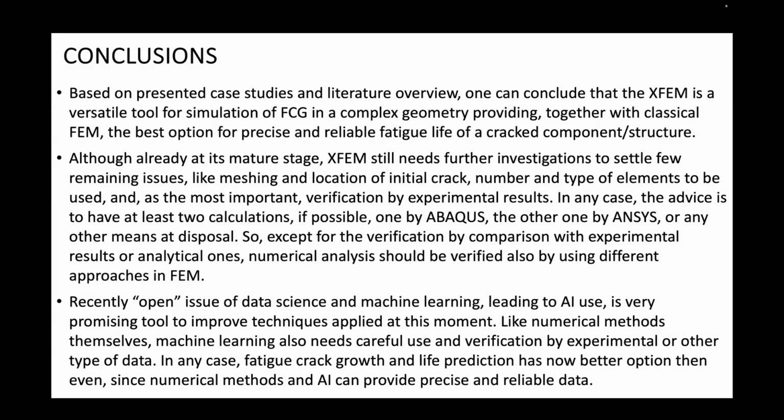But a couple of decades passed, and then automatic remeshing emerged with acronym, which is really a good one, SMART. And I don't dare to try to say what it means, but in any case, it is automatic remeshing as crack grows, so you don't need to do anything manually. Of course, it would be impossible after each crack step to change the mesh. That would last for 4 years.